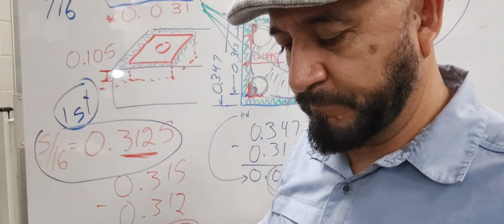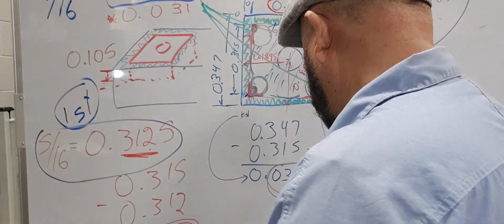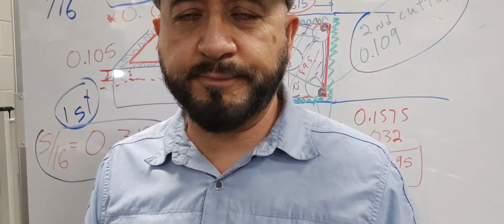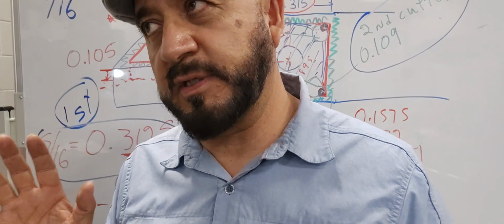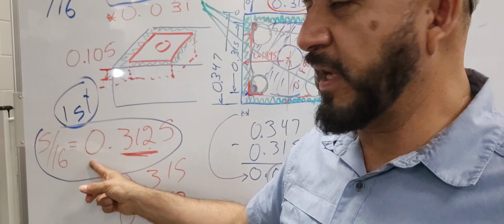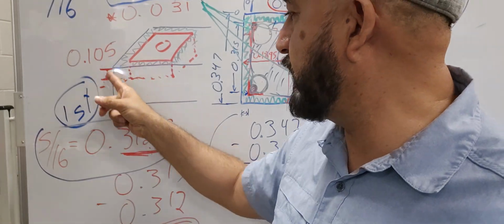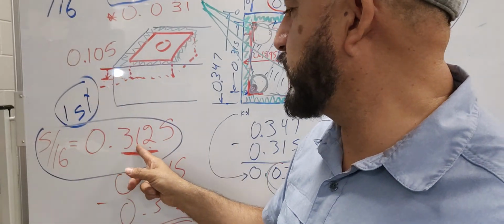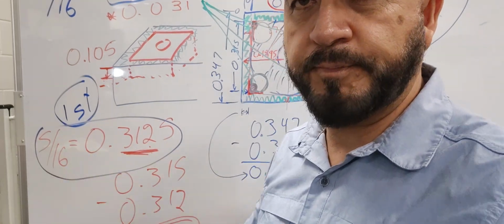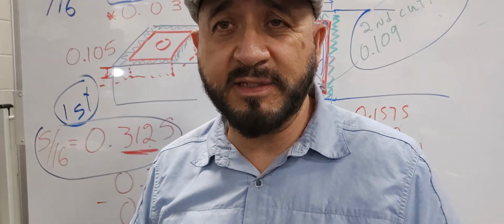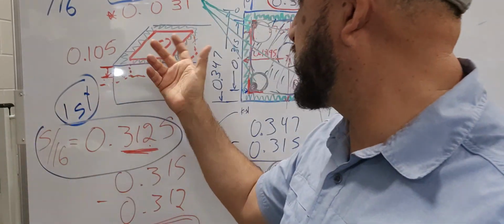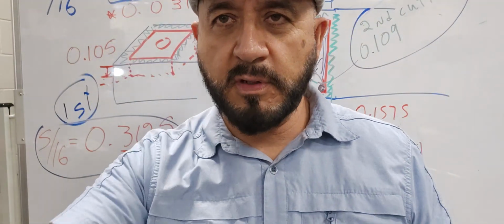Okay. So let's go ahead and do it. I'm gonna pause this video and I'm gonna set up everything in the machine so we can do that first operation. Go down 105 using a 312 thousandths or a 5/16 tool. And we'll create the first part of the pocket. We'll get the most of that out as this is milled out. All right, let's do it.